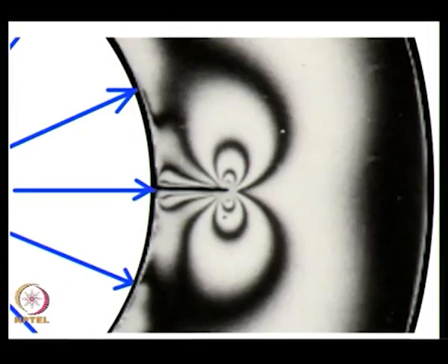Because when you are really looking at practical problems, they are all finite geometry. Analytical solutions are provided only for infinite geometry, or when you have a series of repeated cracks. Only for such nice problems do you have expressions for stress intensity factor. For any other problem, when you have a crack lying in a stress concentration zone or in a finite geometry, you have to depend on either a numerical technique or an experimental technique. In the case of an experimental technique, you will have to use appropriate equations to process the data, that becomes very important.